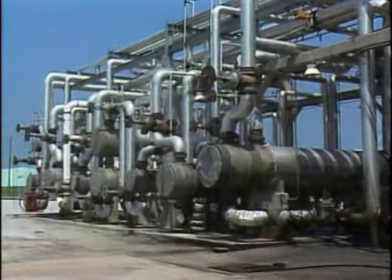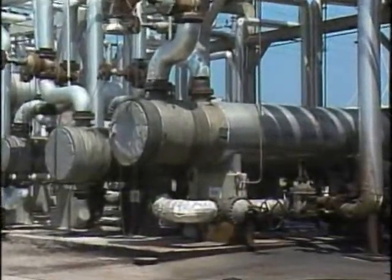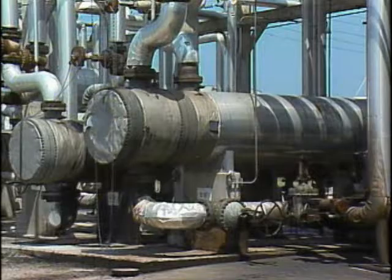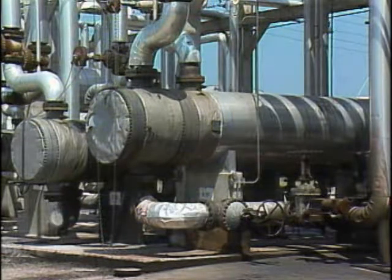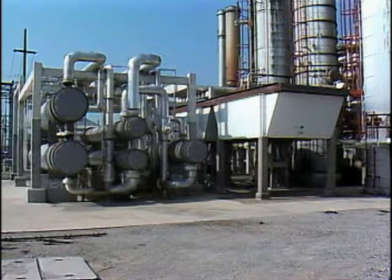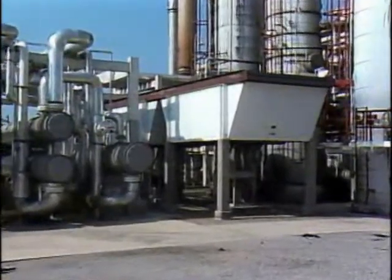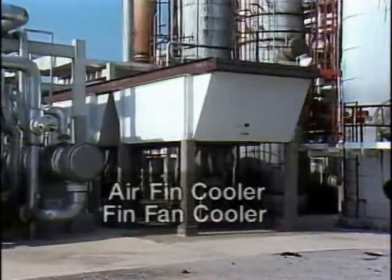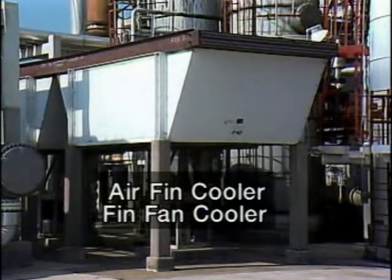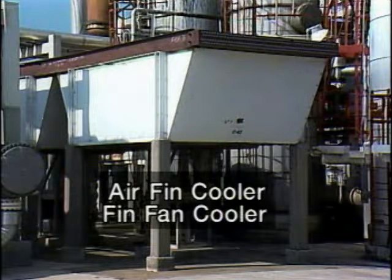In a typical heat exchanger, heat is transferred by conduction, convection, and radiation from one fluid to another. As a general rule, most heat transfer occurs by conduction and convection. To get a better understanding of how heat transfer occurs in a heat exchanger, we'll use this heat exchanger. It's called an air fin cooler, or a fin fan cooler. It's used to transfer heat from a process fluid to the air that flows through the cooler.